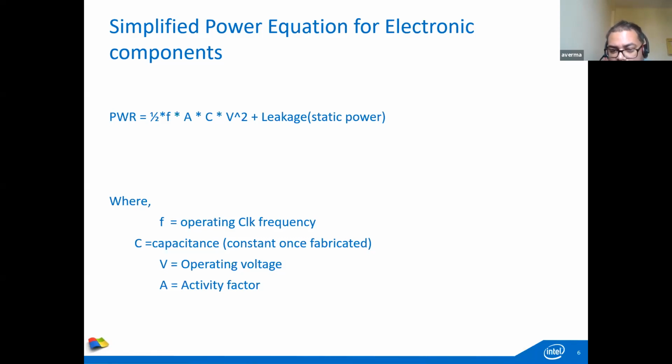So you go for a higher frequency only when the load demands that. If the load does not demand that, you go to a lower frequency. How do you know whether the load demands that or not? You keep monitoring your CPU utilization. For example, you are doing some task at 2 gigahertz and you find that your CPU utilization is 90%, so you bump up to maybe 2.4. You find that it's still at 90%, you can bump up again.